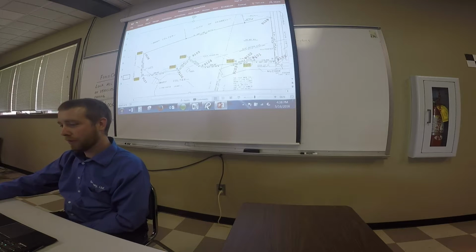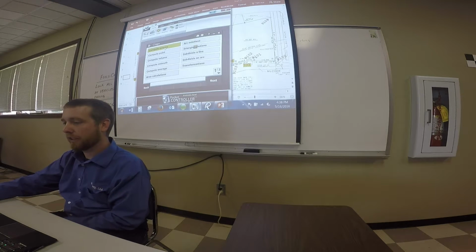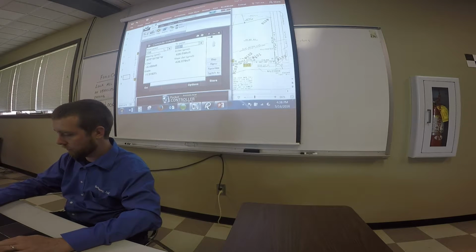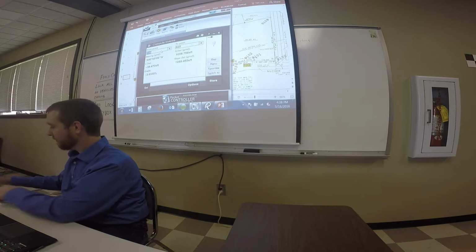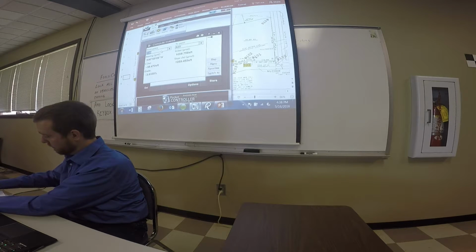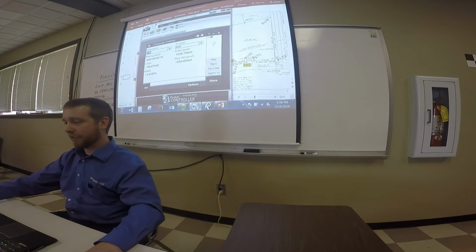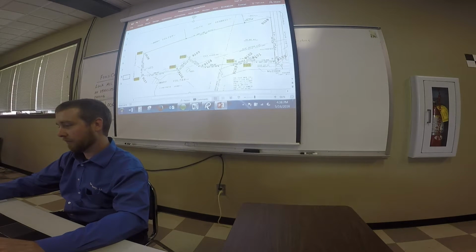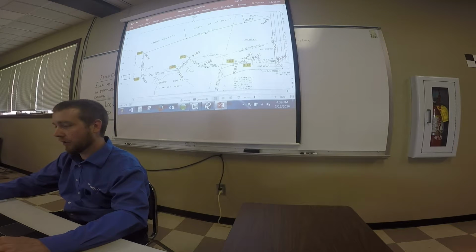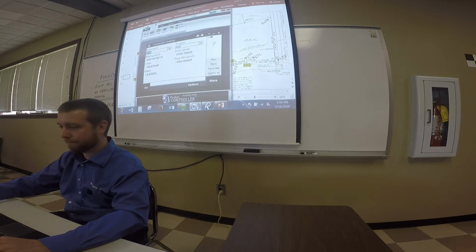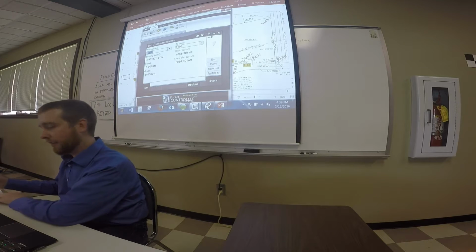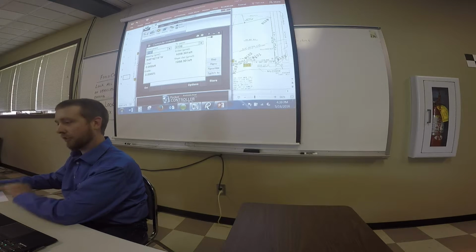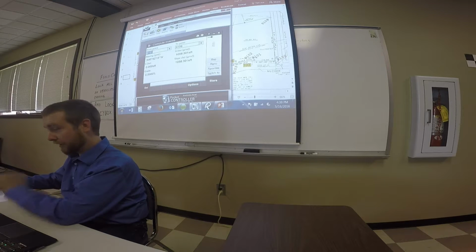Sorry, we're going to do 103 to 845. We'll go with inverse. It's 1,058.76, and that's from the pins that we actually shot. Now our points that we had given to us are 9101 to 9108, which gives 1,058.3. So we're 4/10 difference across the entire 10-acre site. That's pretty good for finding pins. So we'll hold that and go with it for now.